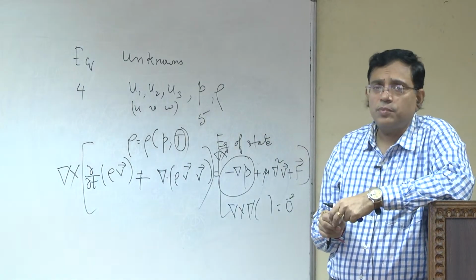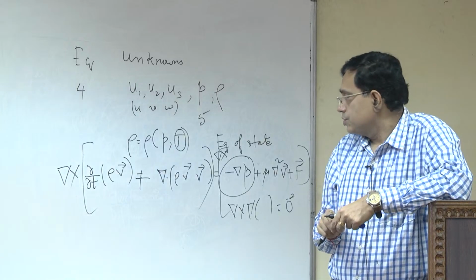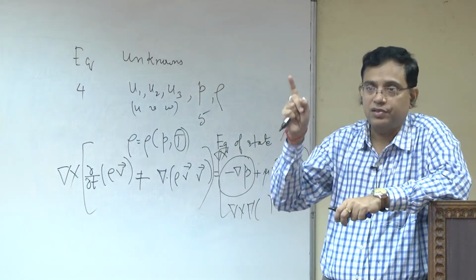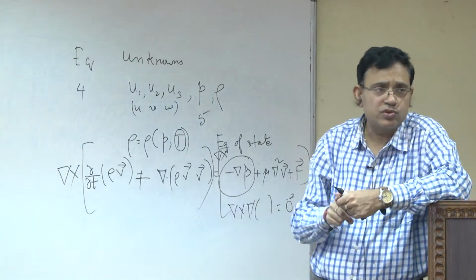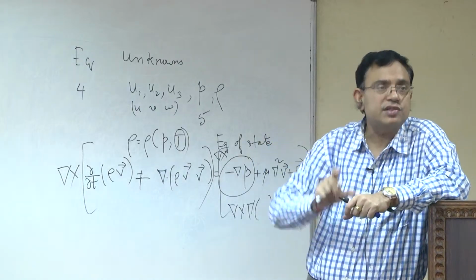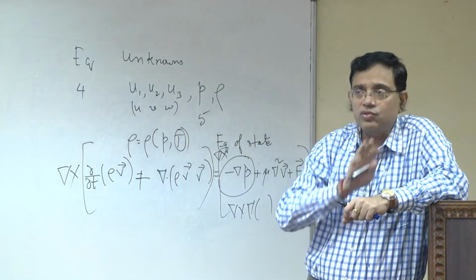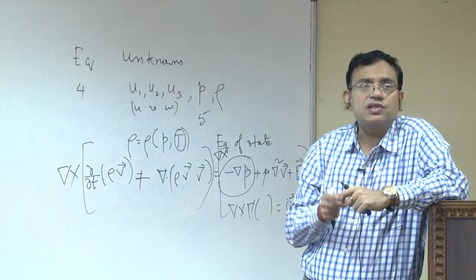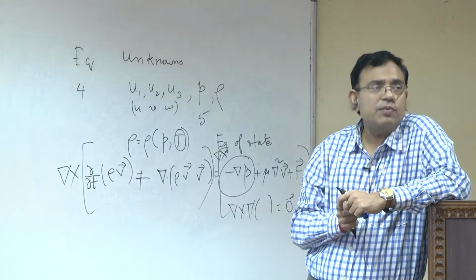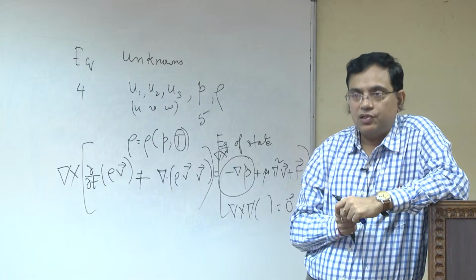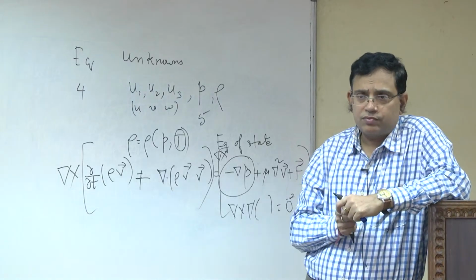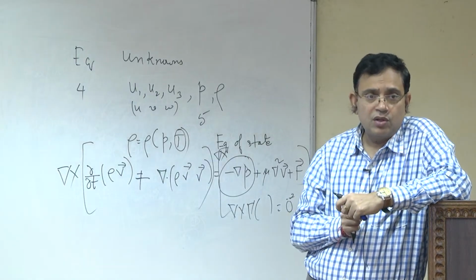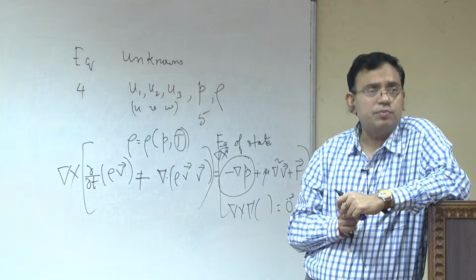Typically you cannot just deal with vorticity in an isolated manner. Vorticity is connected with stream function in a 2-dimensional incompressible flow. That is called the stream function vorticity formulation. We will not get into that. It is always good to learn, but it has its restricted appeal, because for every problem you have to give boundary conditions, but vorticity is not your fundamental physical variable, nor is stream function. Your fundamental physical variables are velocity and pressure.